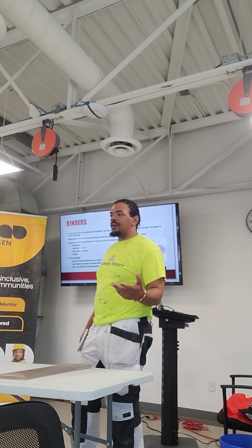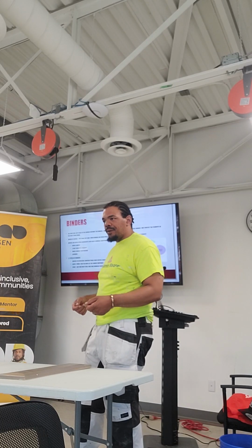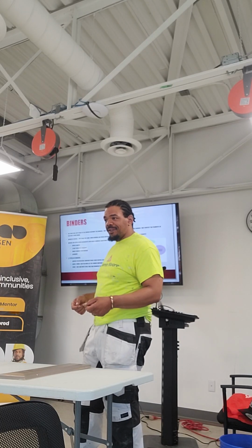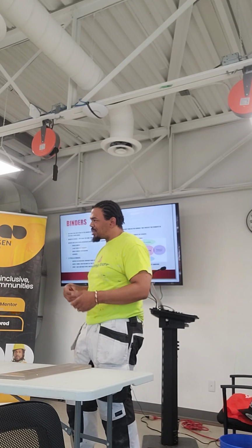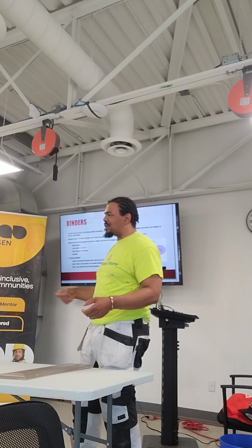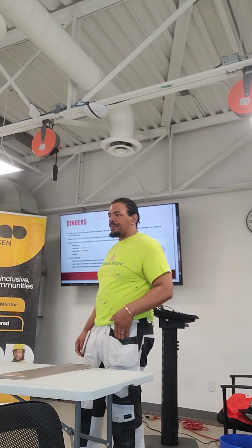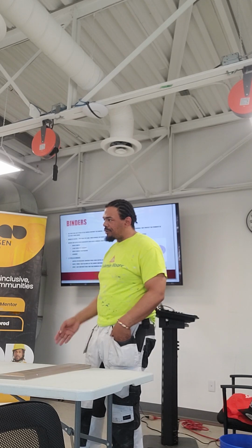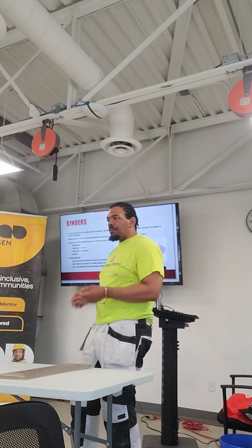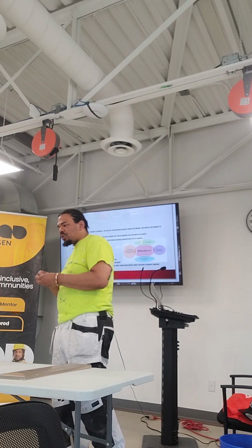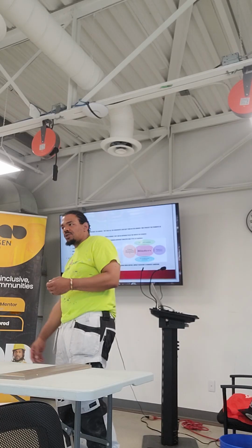Water, food coloring. You ever try to paint with food coloring? Yeah, you've done that before? Yeah, on construction paper, you use food coloring. When you make paintings with the kids, they use food coloring. But if you try to put food coloring on a piece of metal, what happens? It slides right off. There's no binder. It's a color, it's a pigment, but there's no binder. There's nothing that will glue that surface and make it stick to the surface that you're putting it on.